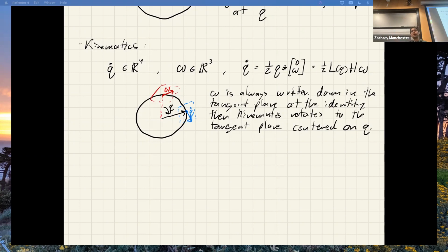In the attitude case, there's a paper from the 60s by a guy named Stuelpnagel, where he proved mathematically that there's no globally smooth and non-singular 3-parameter attitude representation. So those are the words. You can use 3 numbers, but somewhere it's either got to have a jump discontinuity or a singularity. That's the trade. If you go up to 4 dimensions, then it can be smooth and nice and continuous everywhere. And that's why we do this. Rotation matrices are also smooth and nice everywhere, but they're 3x3 matrices with a lot more constraints and they're more annoying to deal with. So these are the way to go. These are used in computer graphics, aerospace, robotics.